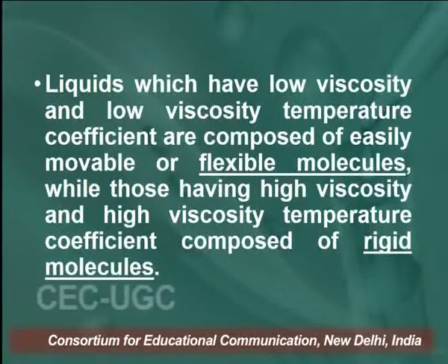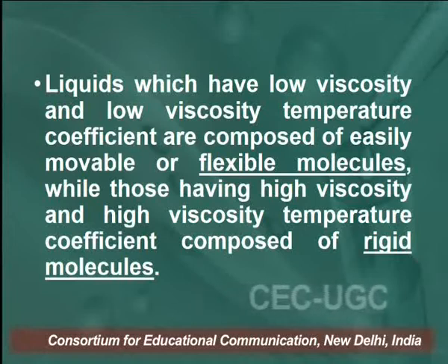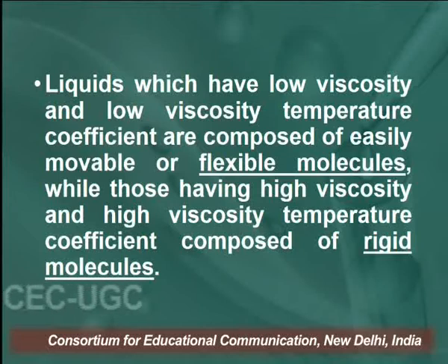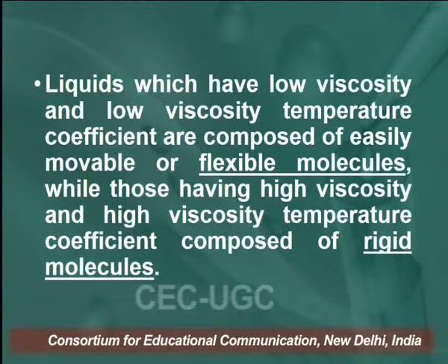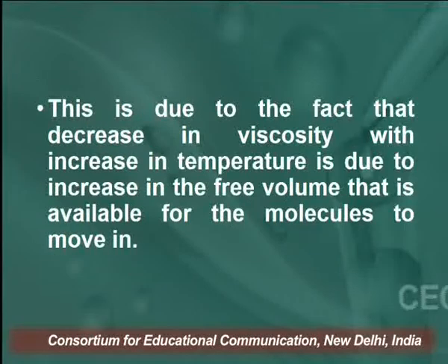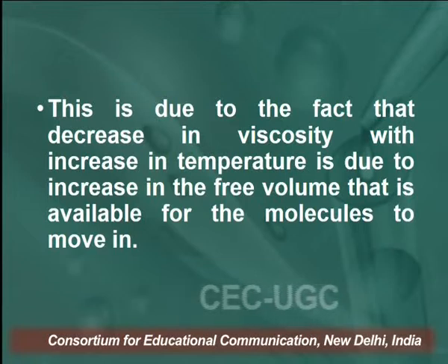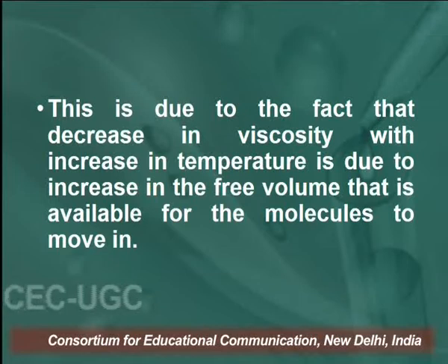So, the liquids which have low viscosity and low viscosity temperature coefficient are composed of easily movable or flexible molecules, while those having high viscosity and high viscosity temperature coefficient are composed of rigid molecules. This is due to the fact that the decrease in viscosity with increase in temperature is due to the increase in the free volume that is available for the molecules to move in.